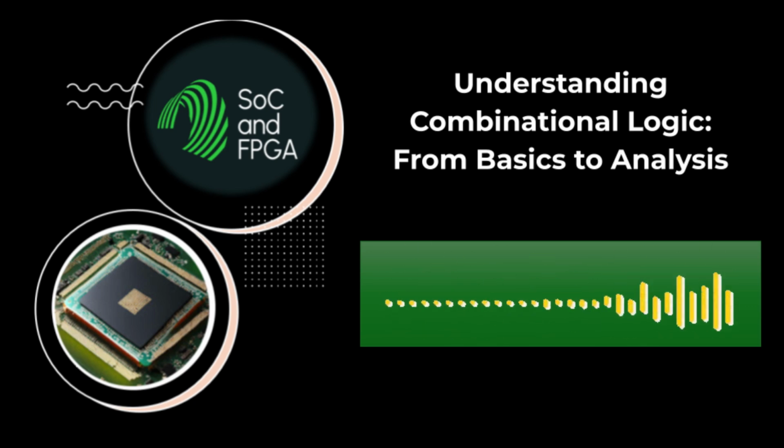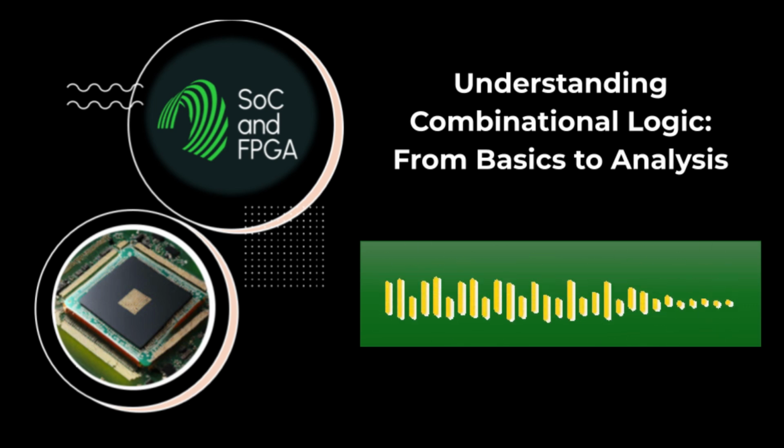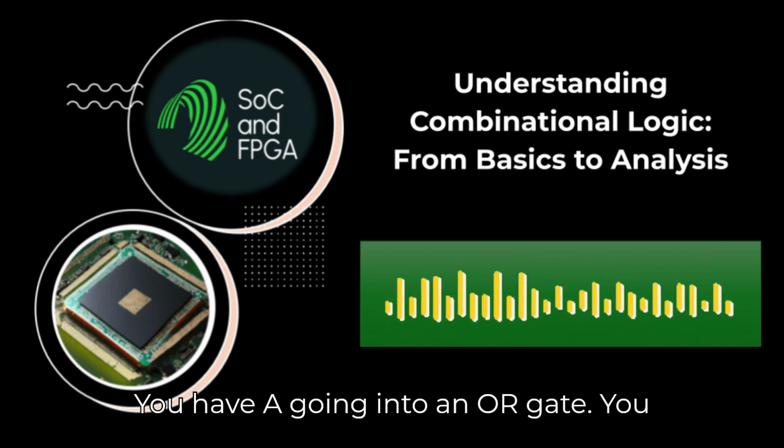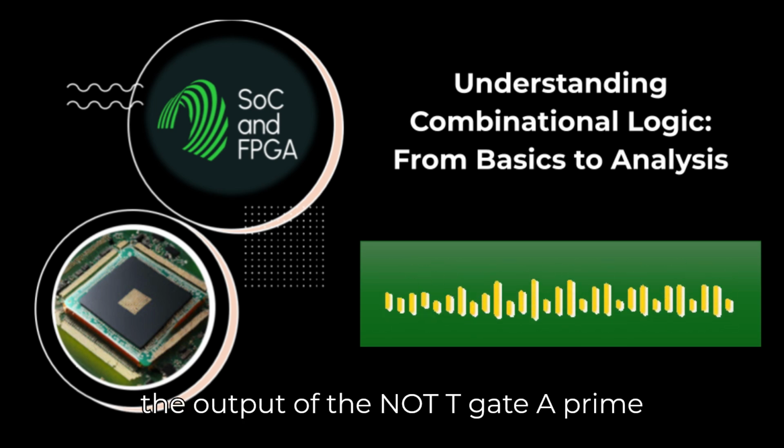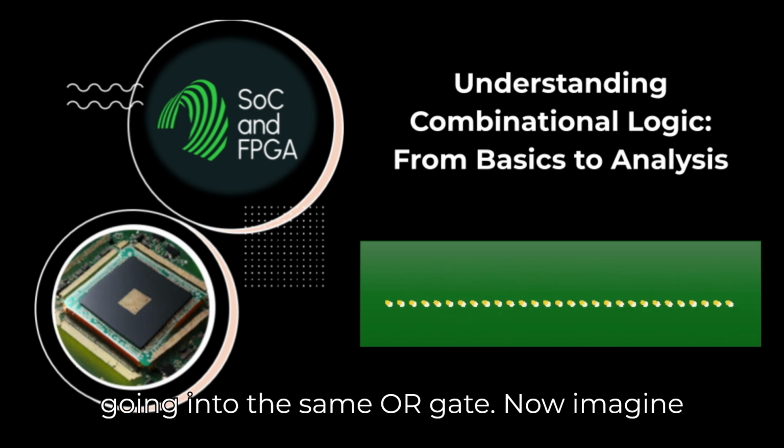If A is 0, A prime is 1, so F is 1, always 1. Correct. But build it with real gates. You have A going into an OR gate. You also have A going into a NOT gate. And the output of the NOT gate, A prime, going into the same OR gate.